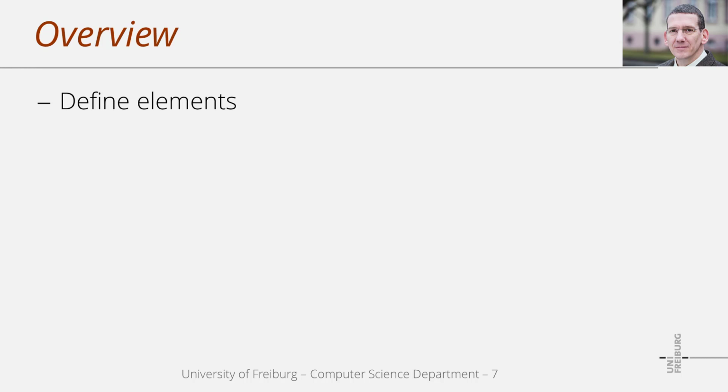So the concept starts with the elements that are formed by particles. Very often we use so-called simplices as elements, which can be seen as the simplest shape in a certain dimension. So for 1D objects we would use line segments, for 2D objects we use triangles, and for 3D objects we use tetrahedral elements.